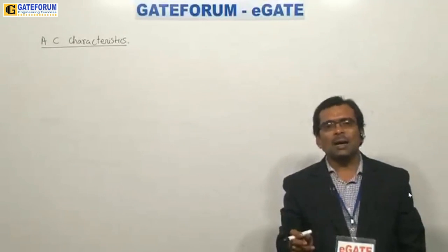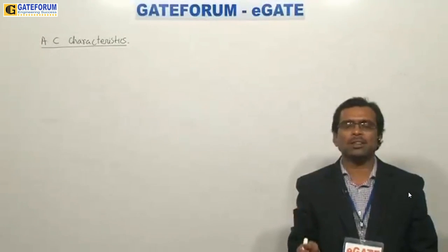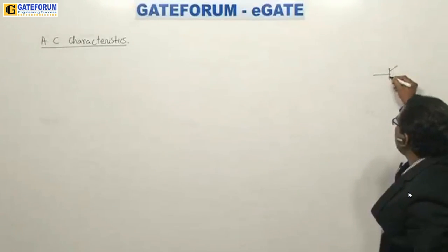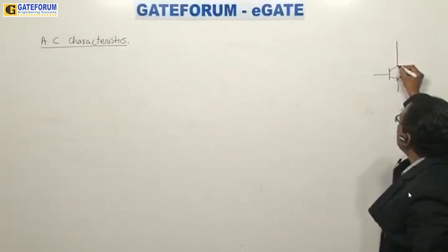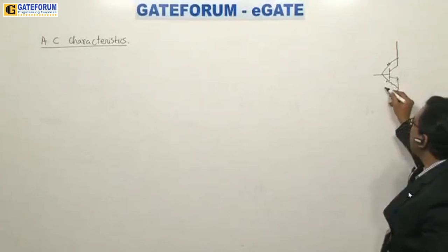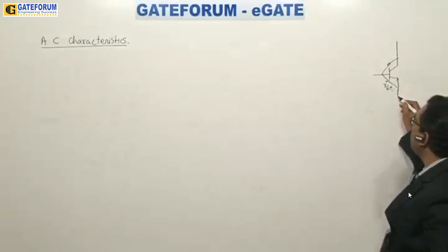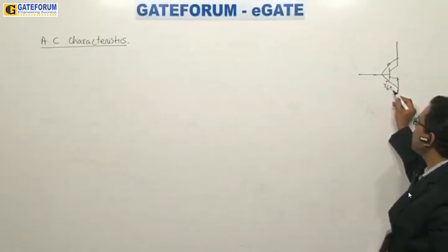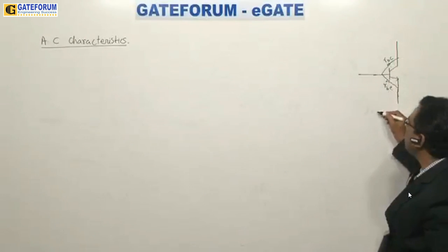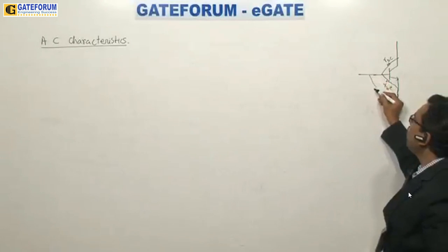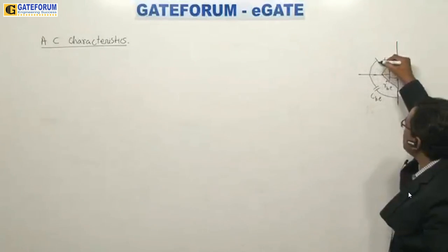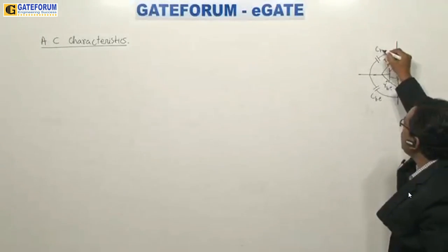Why? Because the op-amp inside always has the same transistors we have studied earlier. At high frequencies, the transistors will lose their property of amplification because of poor reactance provided by the stray capacitance. Under forward bias, a PN junction will have forward resistance RBE, and under reverse bias, RBC. Under forward bias, a PN junction will also exhibit a capacitance called CBE, and in reverse bias, a transition capacitance called CBC.